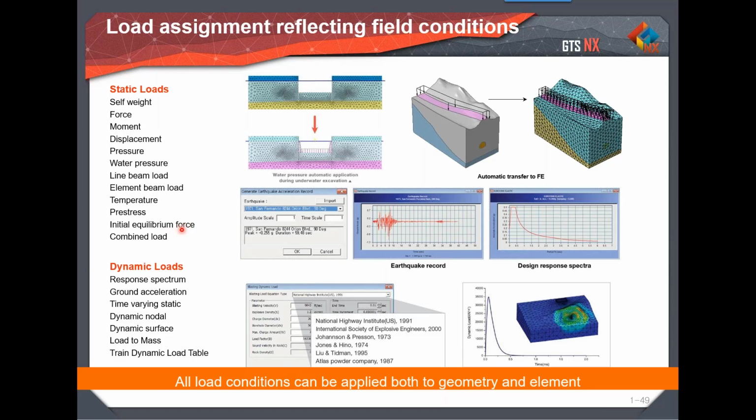And the important thing is you can combine all the kinds of loads using various factors, and you can apply the combination load. There are no codal provisions in this software, but you have all the loads that you can apply. So based on the codal provisions, you can apply the factors manually, and you can get the combination load. And once the combination load is achieved, you can run the analysis and get the results accordingly.